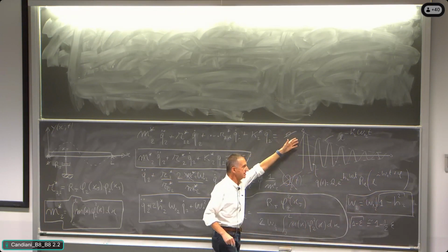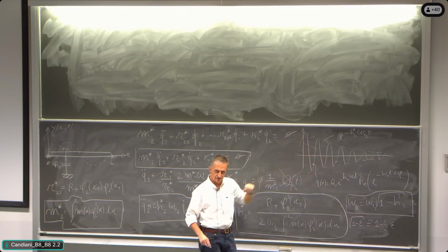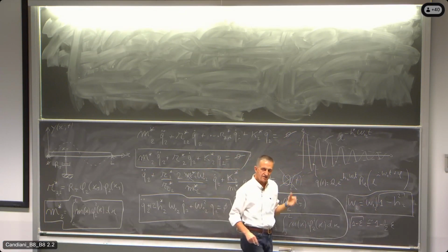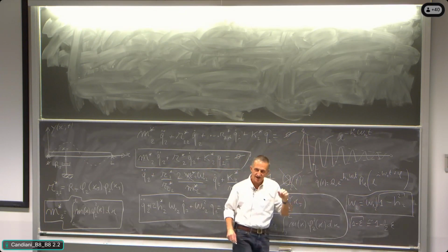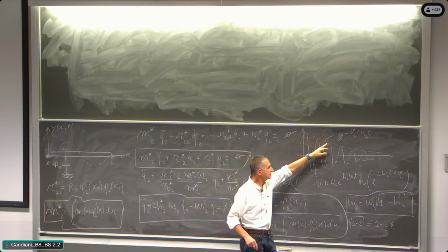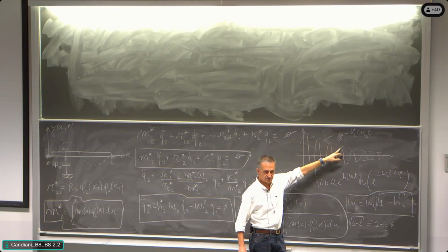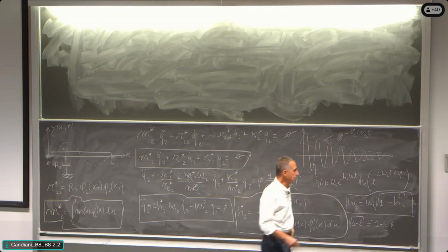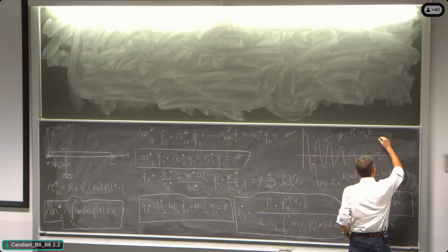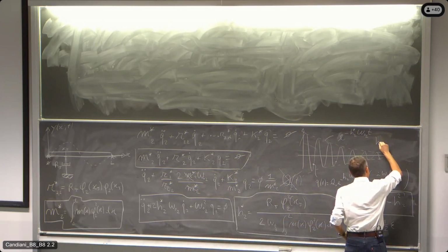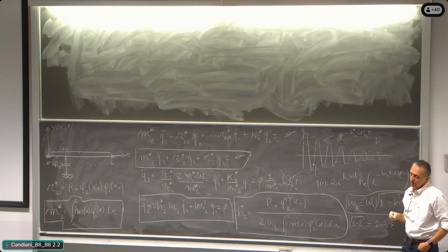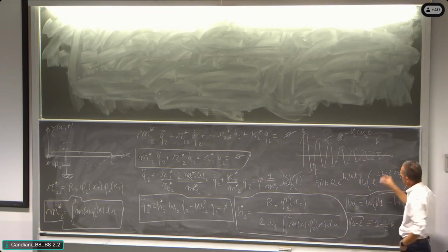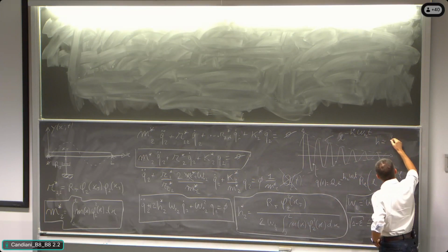What is the non-dimensional damping of a system that is decaying in this way? We must have the numbers. How many cycles does it take to make 1/2 amplitude? It takes 1, 2, almost 3. If it takes 1 cycle to make 1/2, the non-dimensional damping is 10%.